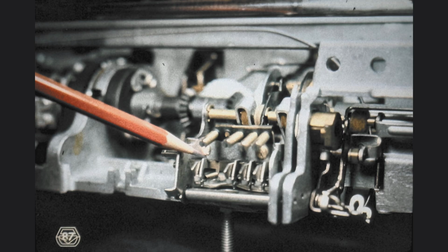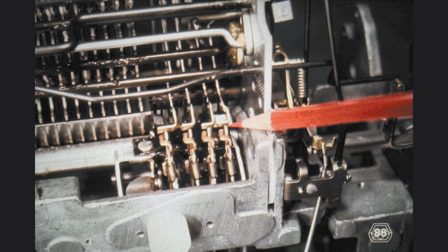This means that this operational interposer latch plate not only holds the position of the interposers front to rear when the interposers are at rest, but also controls the vertical position of the front end of the operational interposers. The clearance at the indicated point between the index keylever pawl and the interposer should be approximately 0.89 mm. We change the vertical position of the interposer latch plate, and thus of all of the operational interposers, by loosening the screws which hold the plate.